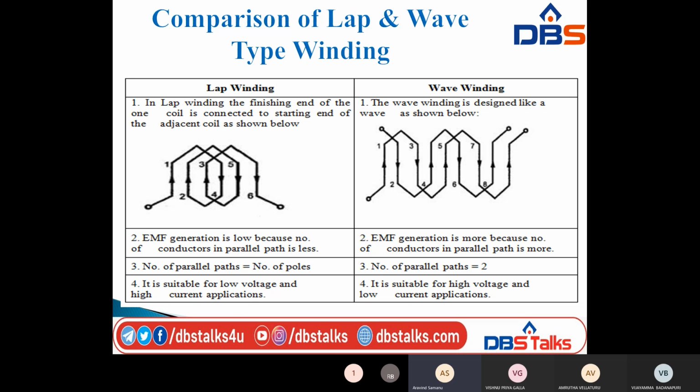And the fourth one is suitability. I already said that in the lap and wave winding explanation. Lap winding is suitable for low voltage and high current applications. Similarly, wave winding is suitable for high voltage and low current applications.